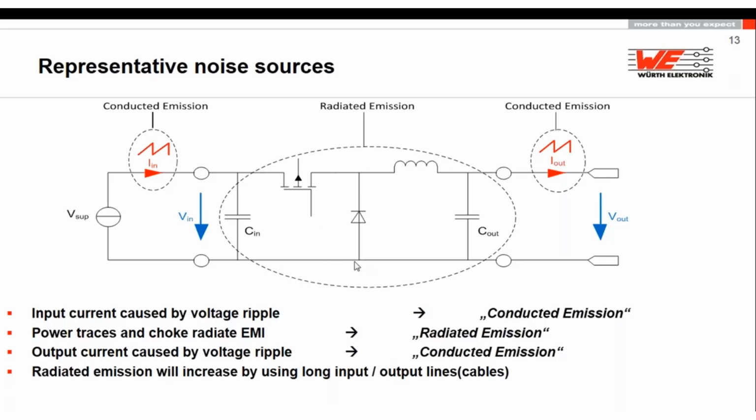As soon as you keep this antenna as small as possible, this is very welcome. And think about it: 1 millimeter of PCB track is exactly 1 nanohenry. So, perfect inductance.